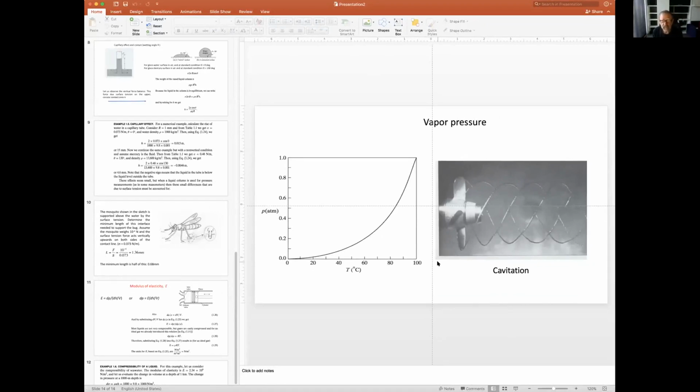So in a liquid, you can say everything, there's equilibrium between different things. So there's equilibrium between the liquid state and then the gas state, okay? However, if the pressure in the fluid is higher, then the gas state cannot expand. You cannot form bubbles, for example, in the water. So, one more time. For example, cooking, if you cook with the pressure cooker, you don't get boiling. You can increase the temperature without boiling the water. Why? Because you're increasing the pressure.